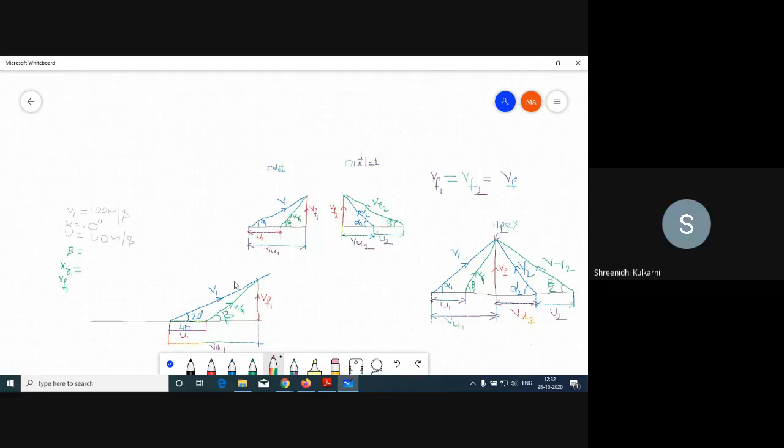Next, in the same velocity triangle, once again I have to draw the outlet velocity triangle, in the same reference line itself. You can answer without any data. So how can we draw the outlet velocity triangle? While solving the problem, definitely they will give the data. Just now I told you, in most of the turbines, the flow velocity is constant. If you measure here and get 10 meters per second, even the